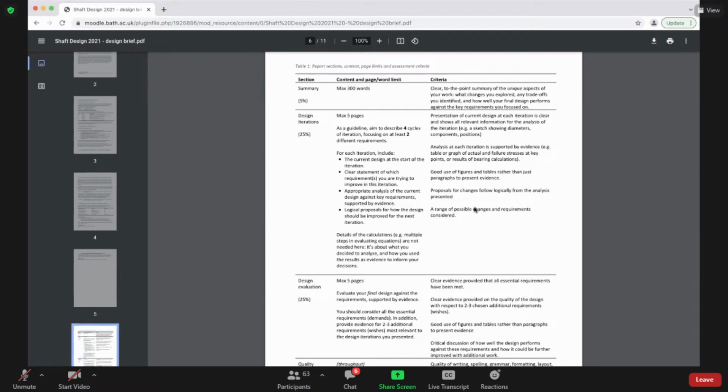But no, I wouldn't say that 60 millimeters was too big. It depends on what loading you've got. The loads you've got depend on what size transmission you've got, because for constant torque, if the diameter is smaller, you're going to get bigger force and bigger loads and bigger stresses. If you're using the less strong material, it's going to have to be bigger. If you're using the stronger material, it can be smaller. So there's lots of reasons why it might be different, but that's not unreasonable.